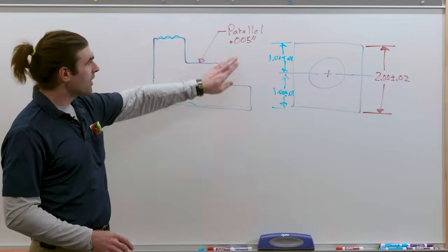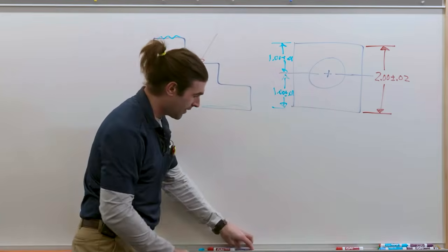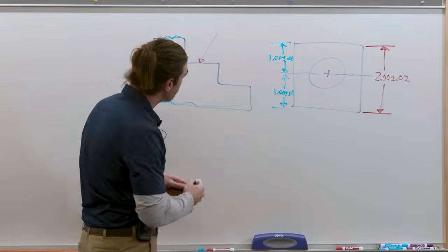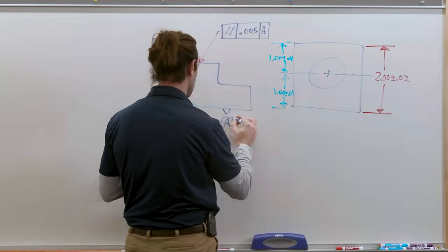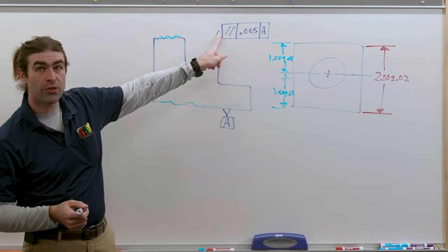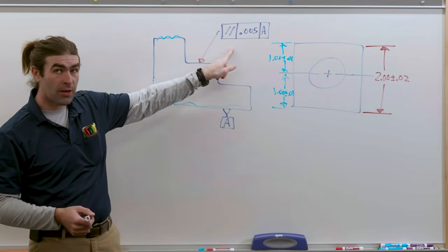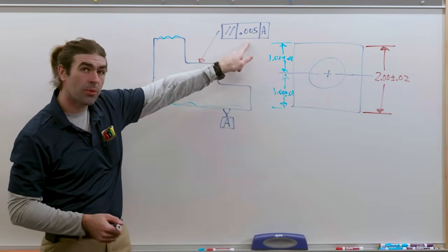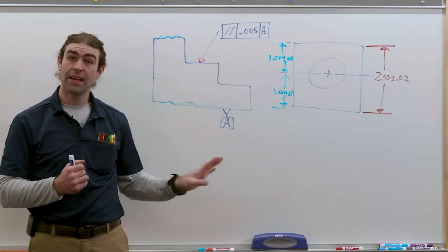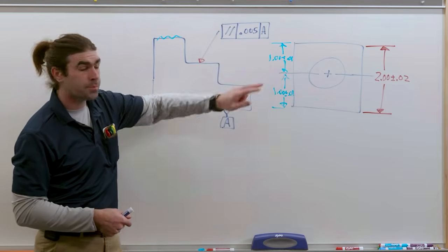So to make this into a proper GD&T callout, we're going to use the feature control frame. Right? So a feature control frame is a box. In this case, it's leader directed. The very first box will have the geometric characteristic symbol. The next one will have the tolerance. After the tolerance will be the datums. In this case, with this particular tolerance, we only need one datum.